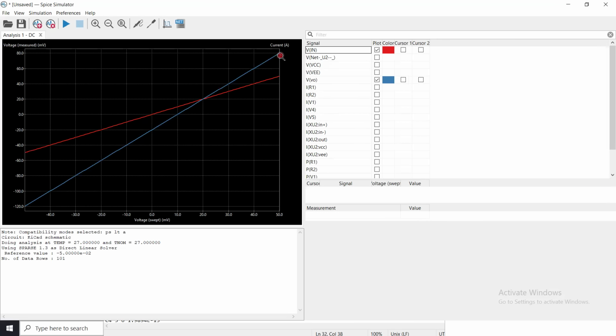Okay, because there is offset voltage also. Don't forget that, right? How about here? If the difference between the two inputs is 20 millivolt, right here, the red point, and then the output here, the blue point, is also about 20 millivolt. Yeah, it looks like that.